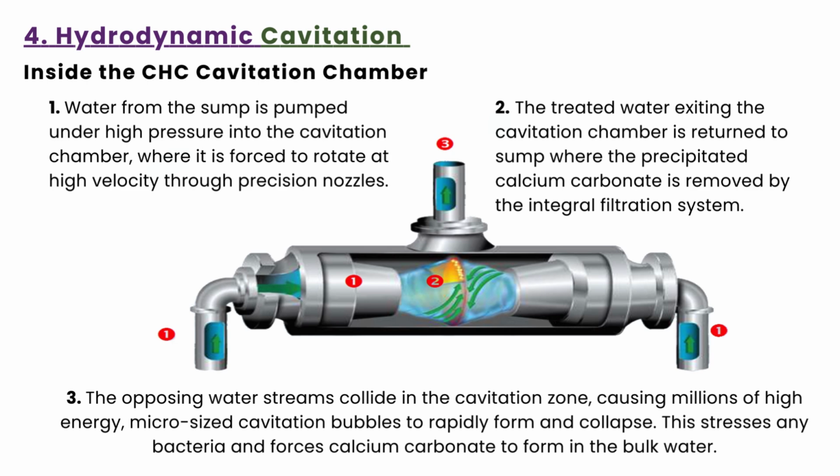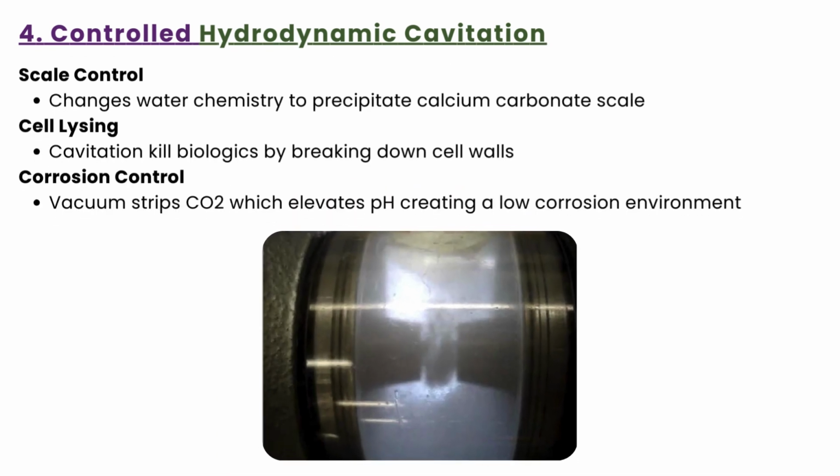And with this hydrodynamics, now the water is getting a lot of swirling, because of which cavitation is taking place. With the cavitation, as per the last video, we are getting the bubbles amplified. And then this is the second picture, if you see, that here in this cavitation you have calcium carbonate scale which is coming out.